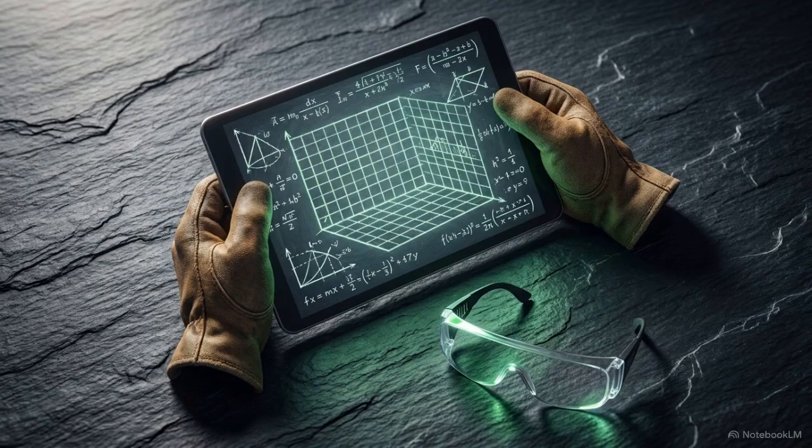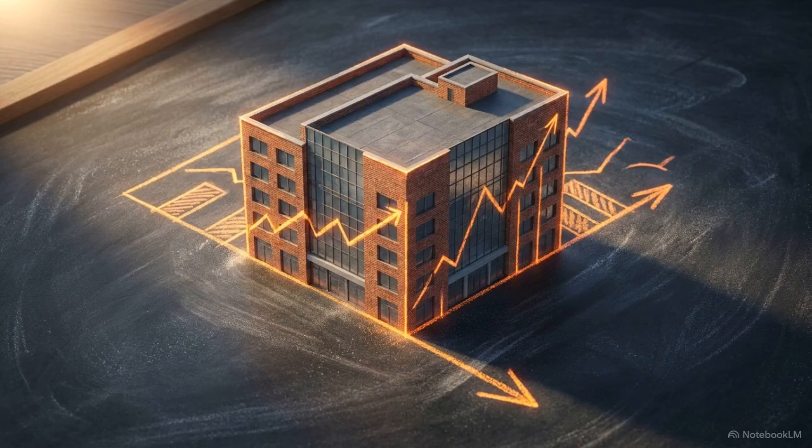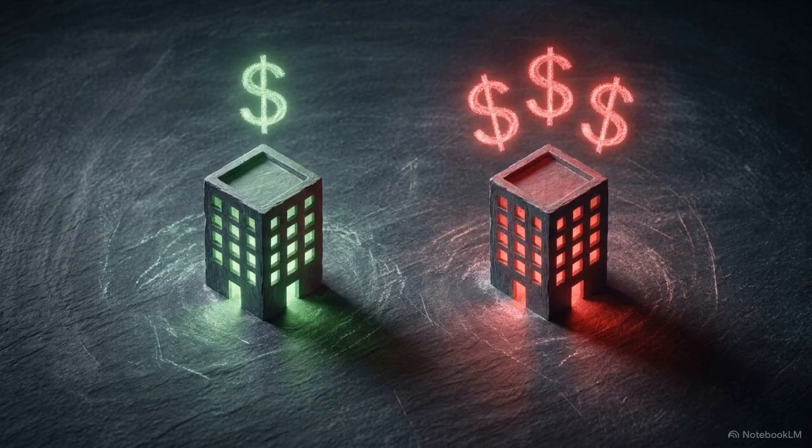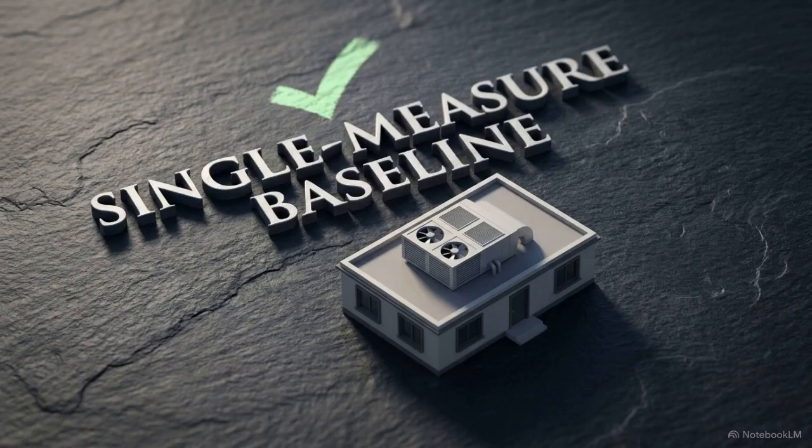Achieving this level of accuracy requires intense computational power and a high degree of user expertise to configure the precise, sub-hourly time steps. These simulations can be structured as forward modeling, which builds a thermodynamic profile from the physical geometry of a blueprint, or data-driven modeling, which uses statistical analysis of actual performance data from an existing structure. Regardless of the engine, building models are designed to compare the economic viability of design alternatives. The vast number of unknown human variables in a real building means these models should not be used to predict absolute future utility bills.